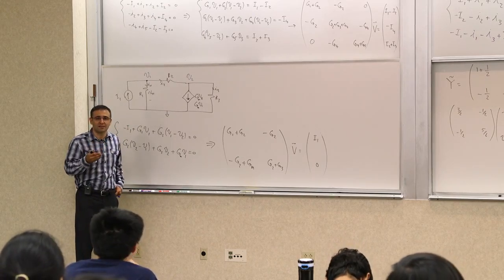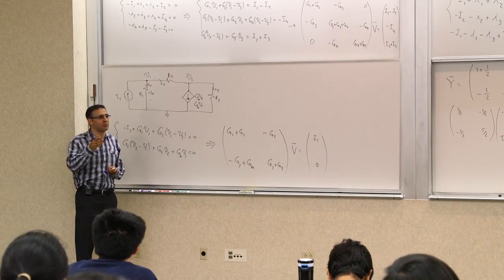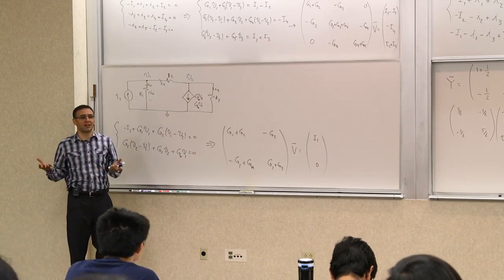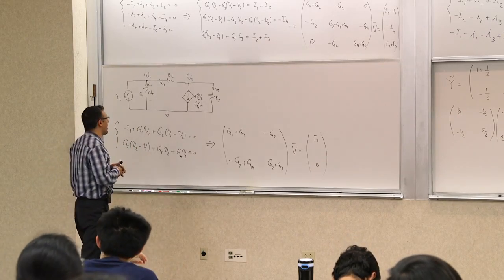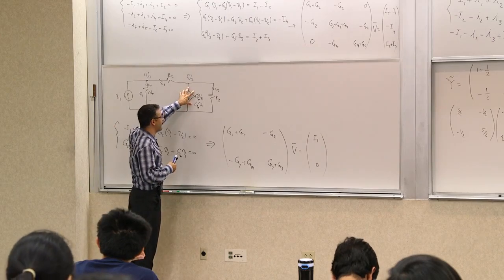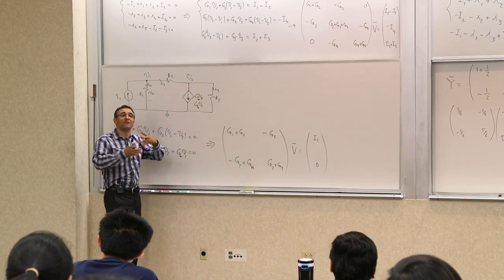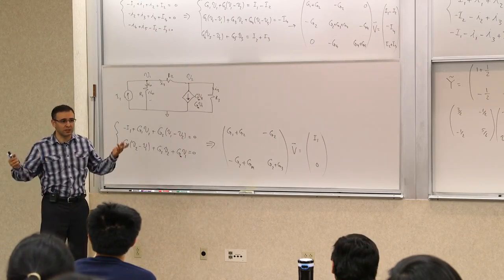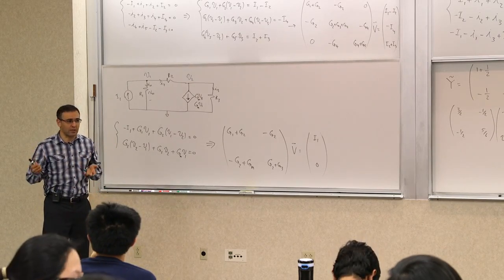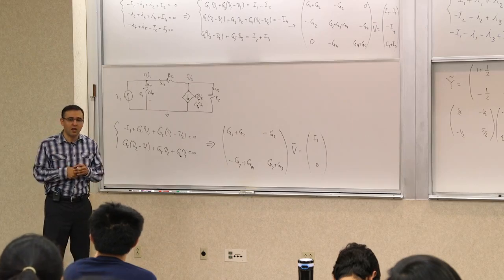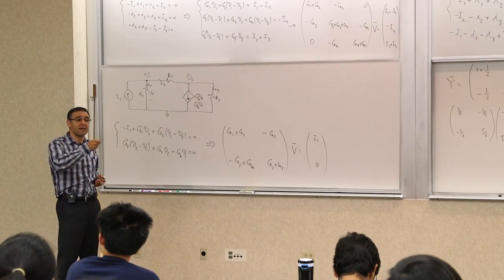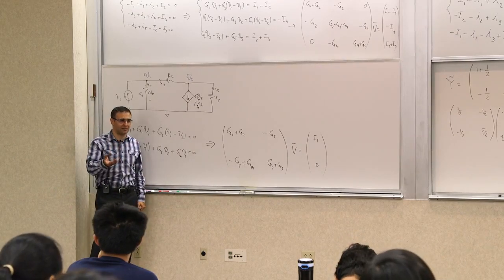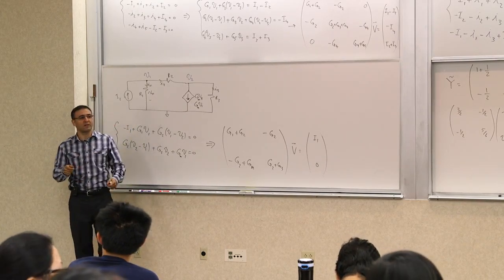There are devices, for example, a transistor is exactly what does that for you. A bipolar transistor, for example, is modeled best as a voltage-dependent current source. Now, the physics of it inside is quite sophisticated, and you can learn it in 114, for example, or 4D. You will learn some of that physics. Different transistors have different physics. So this is done using different physical mechanisms. BJTs do it one way. MOSFETs do it another way.